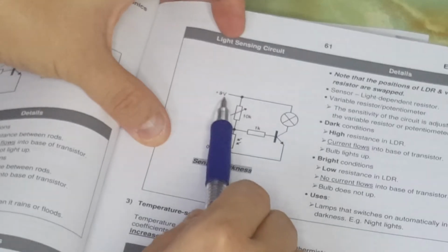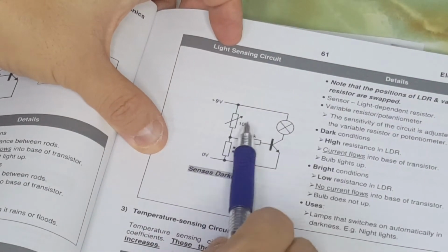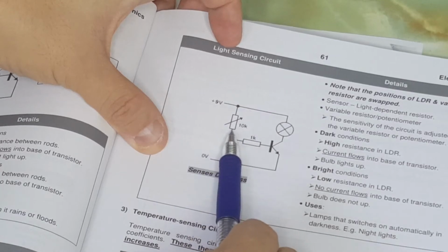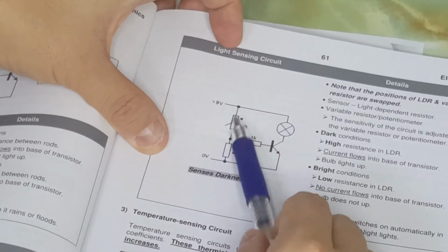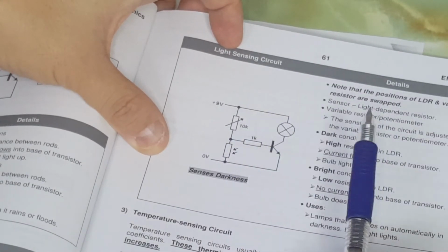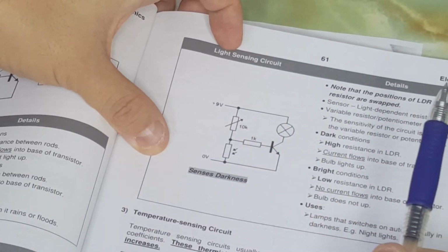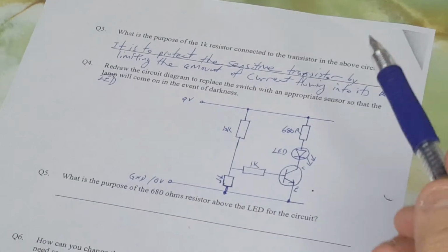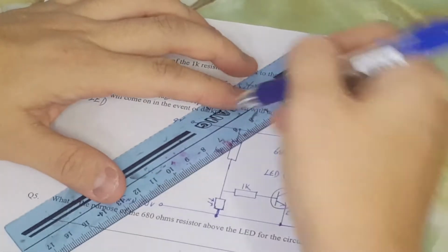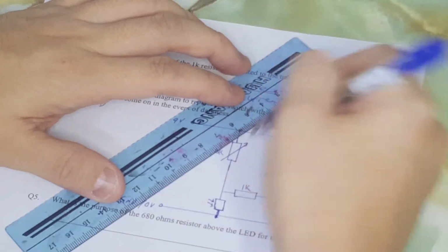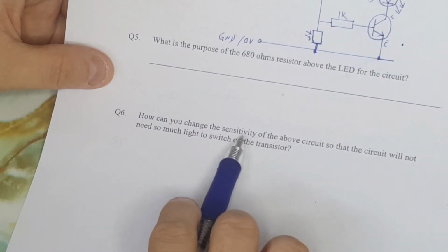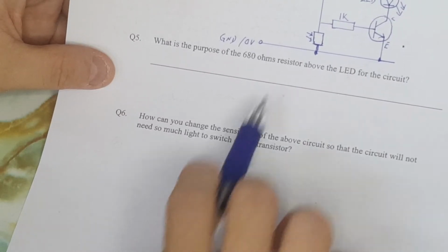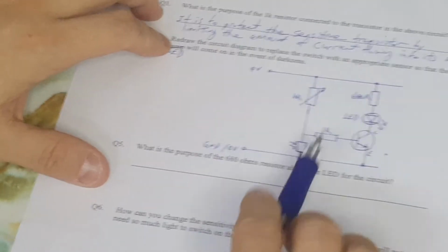What is the difference here is, other than the voltage is not 6 volt, it's 9 volt, is this one here. This is a symbol for a variable resistor from 0 to 10 kilo ohms. So this arrow that crosses over the rectangle, which originally represents the fixed value resistor, now becomes a variable resistor. It will be a good idea to actually provide a variable resistor for your circuitry, like so, because down here you can actually answer the question here to allow for the sensitivity change in the above circuit. So I will explain that in a while.